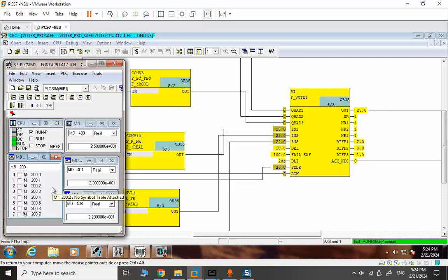So let us just start doing a simple function test. In this case, input 1 is 25, you can see input 2 is 23, input 3 is 22, and 23 as the median is reported to the output. So let us just start, and we just make something run here. Input 3, we change input 3 to 10. It's a deviation. It will create a huge deviation for difference 3. So difference 3 is 13, and as you may remember, the permitted deviation is 10, and each difference should be within the half of this. This is the deviation for signal 3, transfer 3.